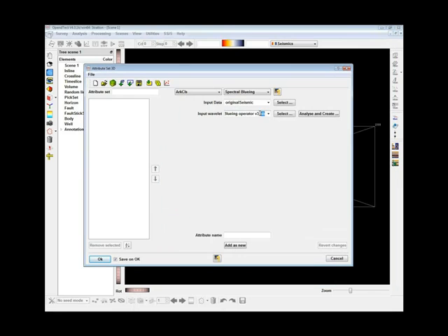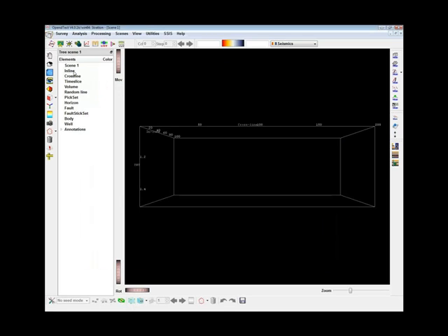And you can see that the bluing operator has been pre-filled in the OpendTect attributes. The only thing that is remaining is to provide a name for this attribute. And the work done by this attribute will simply be to convolve the input volume with my bluing operator. I've specified a name in the attribute set window, pressed add as new to load the attribute definition in memory. Now I can go a bit further and press OK.